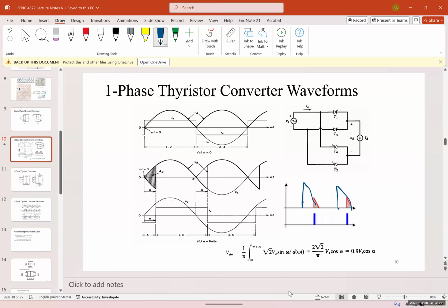And on the upper side, you can see the pulse coming in, which is a control pulse. And at the lower one, you can see that we shifted the pulse a little bit. Therefore, the time that it starts is a little different than what we had on the top. So for this example, this is the pulse that controls the thyristor, and I'll explain more about the thyristors as well. And you can see that now our signal is starting from this point, and again going and starting from this point, and so on.